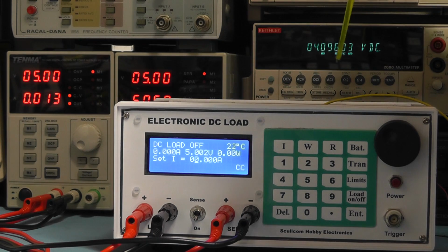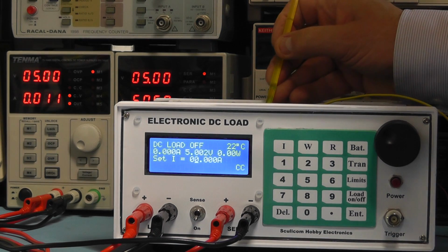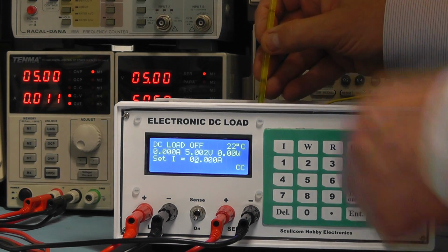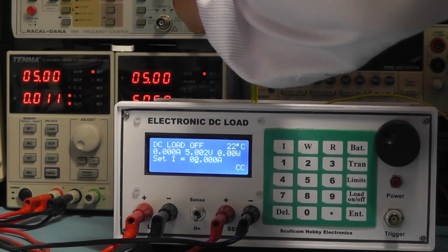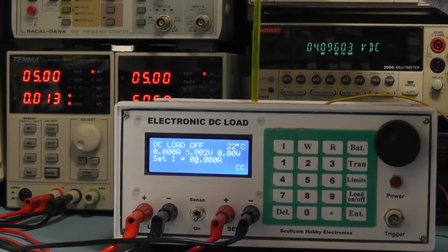So I'm now going to adjust RV3, and we're going to try and get the current you see there on the power supply, the leakage current, to go down to 0. And do this very slowly, because if you take it too far it just upsets the whole calibration. So the trick really is to get it as close to 0 as possible without going past once you get to 0.